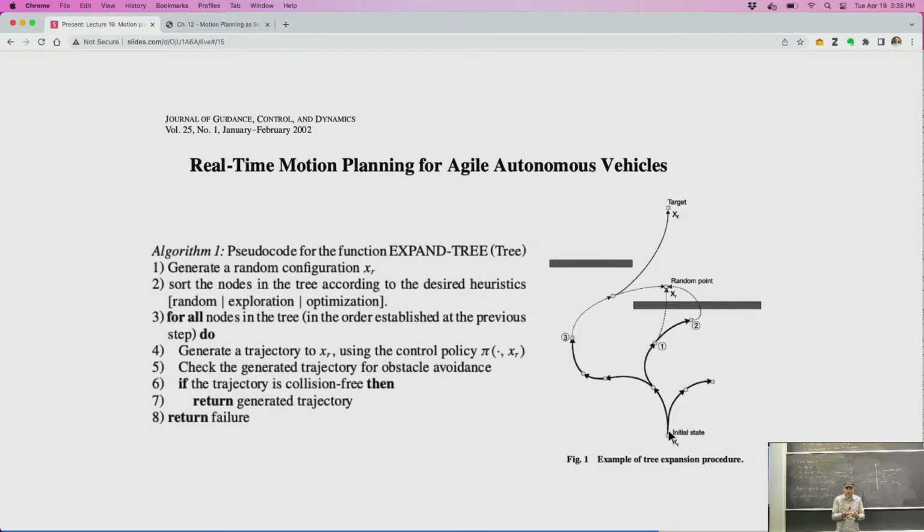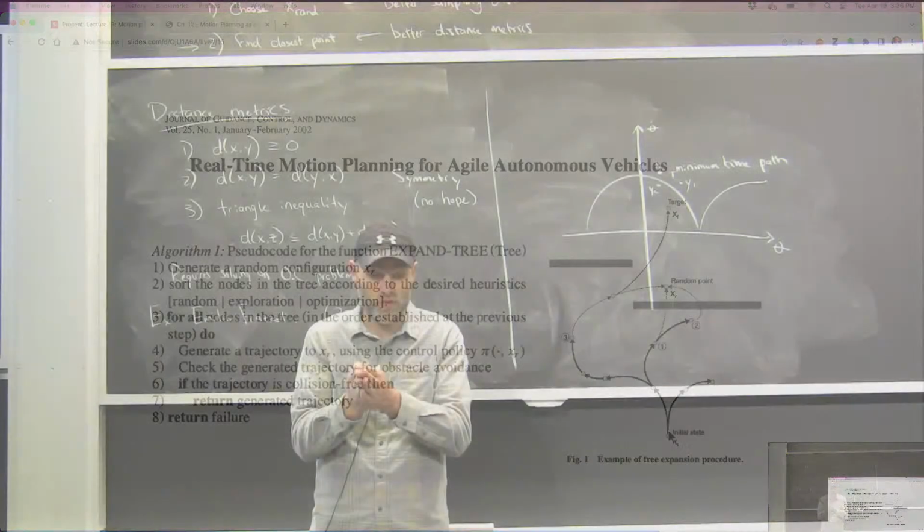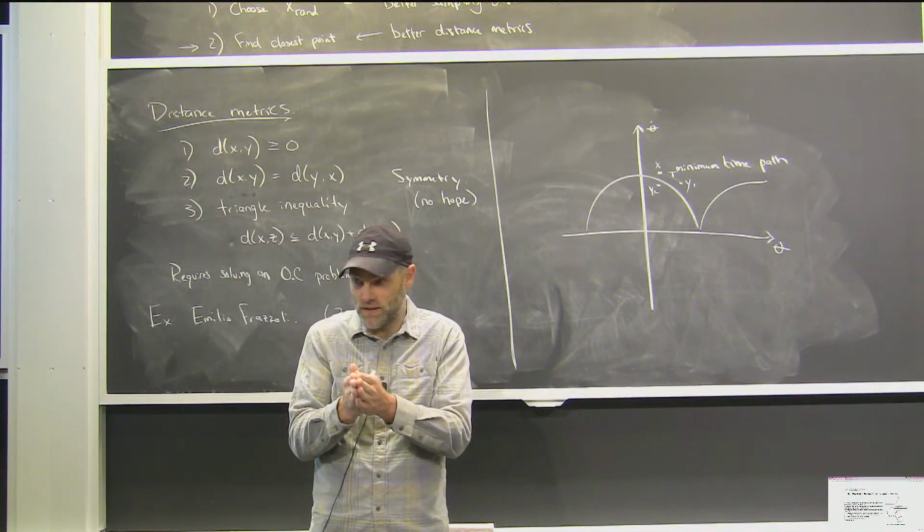So how can you solve value iteration for a helicopter on a big mesh? Well, you have to exploit the fact that there are symmetries in the problem to reduce the dimensionality, like we've often done. If my helicopter is at position X, and I translate the position X, the dynamics are the same, so I can just solve that optimal control problem independent of X, and then translate the solution, drop a dimension. And he did all these tricks. Same with yaw. Yaw angle should drop away. Only a handful of the variables actually matter in the total value iteration solution for the unconstrained problem. They all matter in the constrained problem.